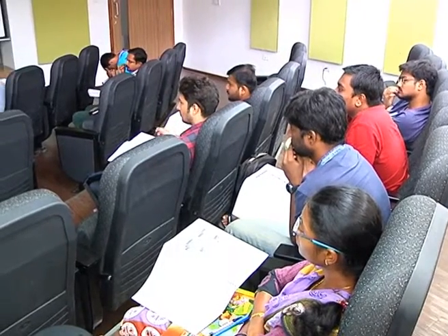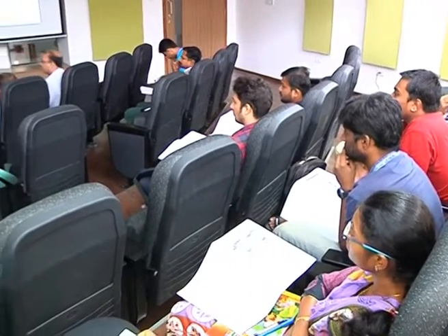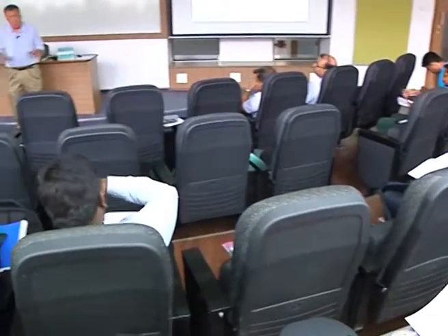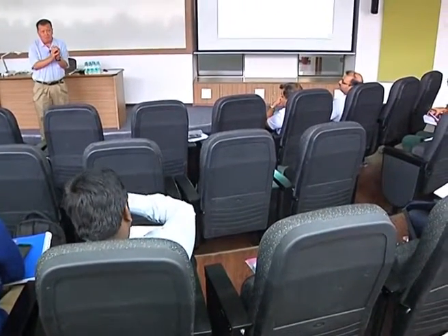Okay, that's a good question. I did not really address it. The Modified Cam Clay is meant for a class of clay called remolded soil. That is a soil that is supposed to have very little cementation. We are talking about real cohesion. There's very little cement in that soil. So it's a remolded soil. That is the reason why the Modified Cam Clay never bothers about the cohesion, which is assumed to be zero.